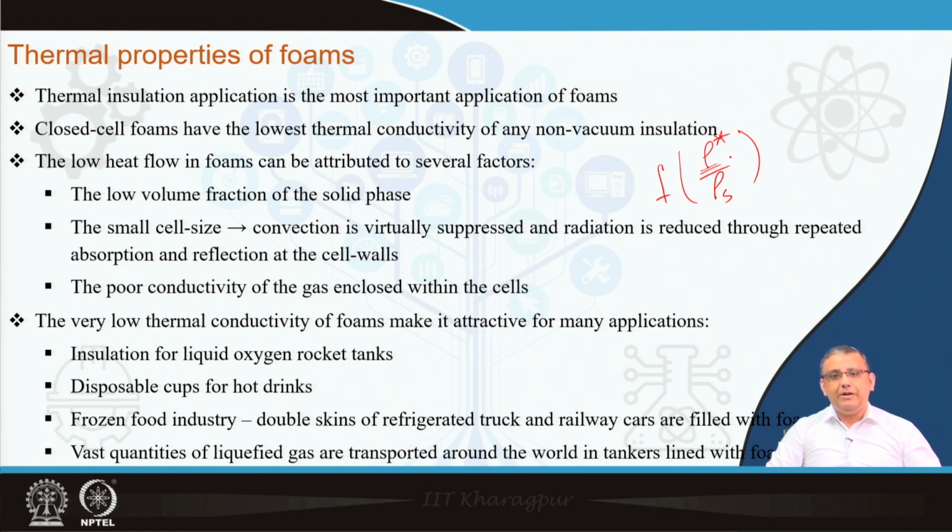And also, because of continuous reflection and absorption, radiation also becomes very low. Also the foams, especially the closed cell foams, may have some fluid, mostly a gas, within the cells, and the open cell foams have air filling up the voids between the cells, and these also have a poor conductivity. So, all in all, foams have low thermal conductivity, and this low thermal conductivity of the